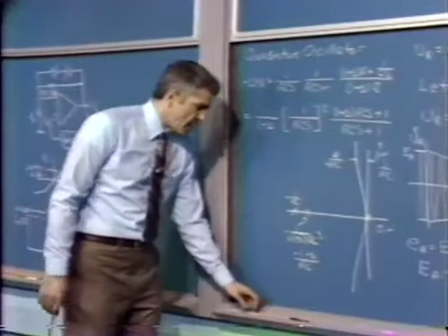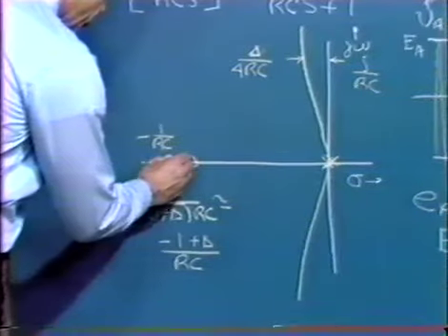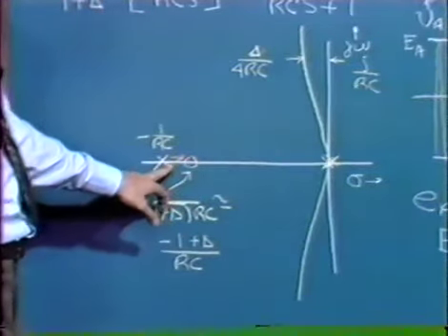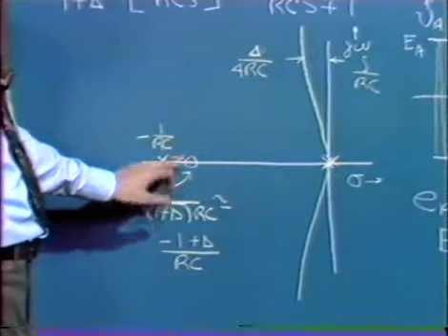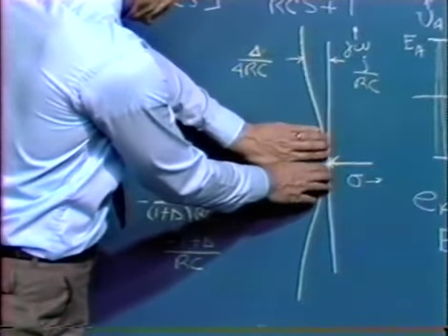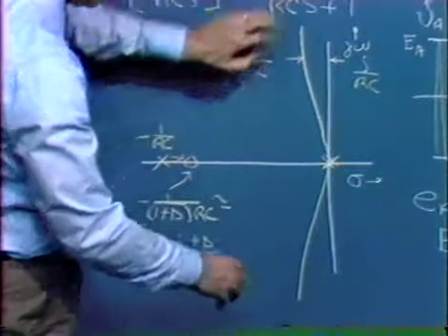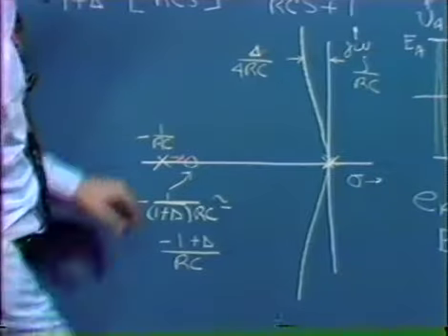Well, the root locus diagram for this setup, of course, is simply that this branch moves toward the zero. To counter that, this is a system where the average distance remains a constant because we have 3 poles and only 1 zero. These branches spring out at right angles, or spring out along the imaginary axis, but they have to come back somewhat to counter the fact that there's a branch moving to the right in the S-plane.